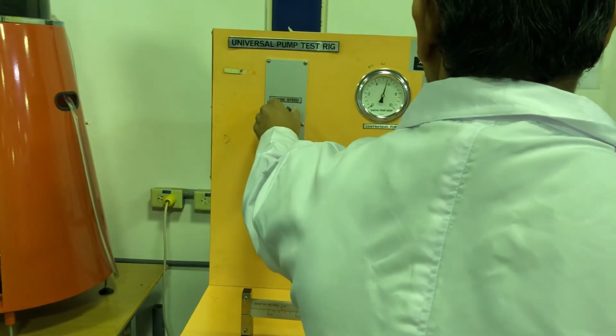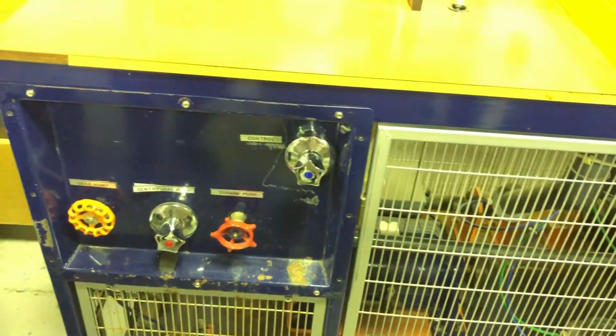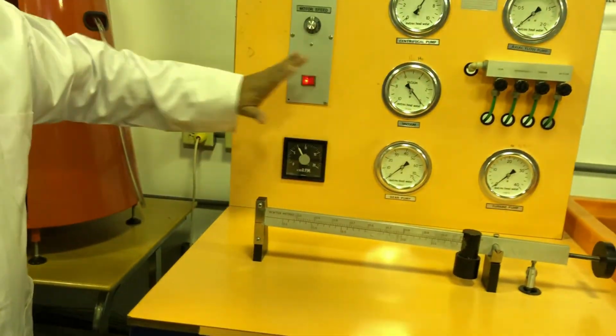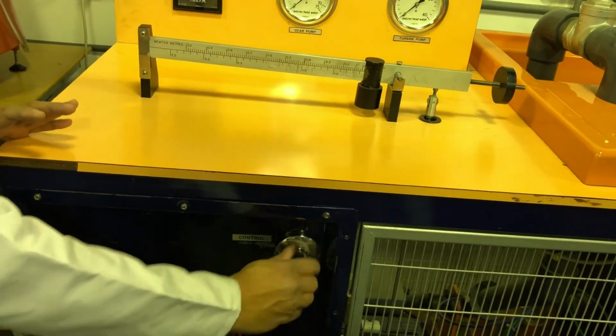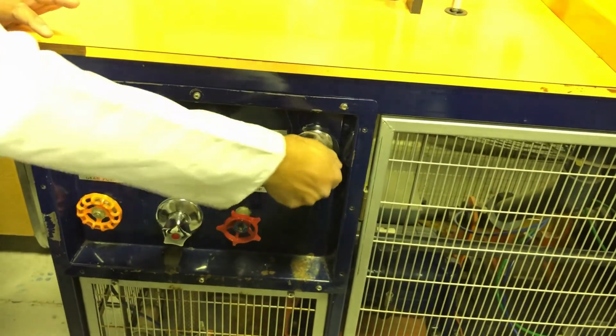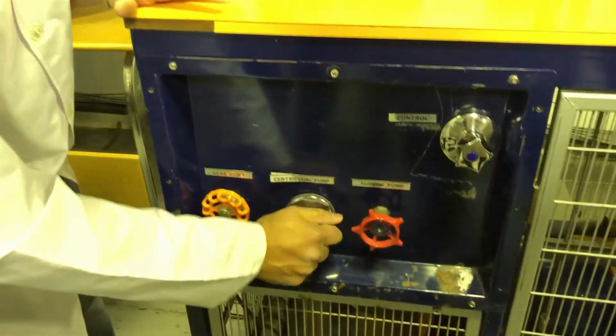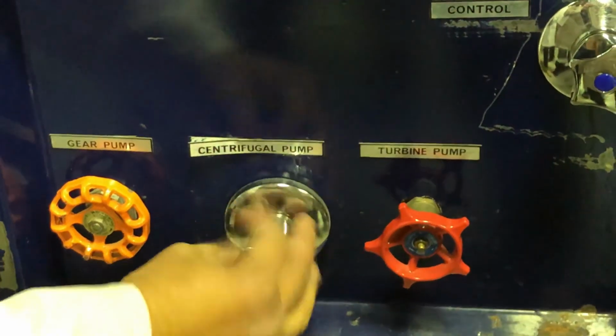now water is flowing. So see here, this valve should be completely open before starting the pump. And which pump we selected? Centrifugal pump. This should be open. It was closed and the torque was maximum. Okay, so this valve should be open. So this is open.